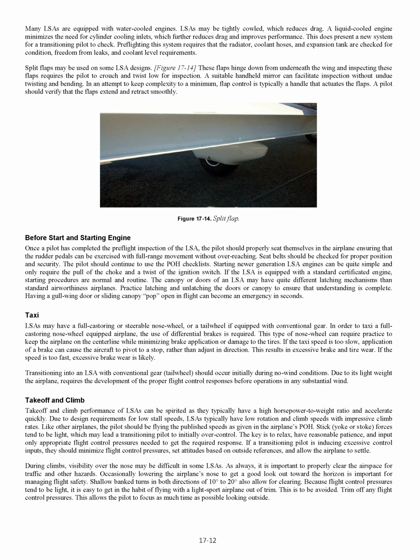These flaps hinge down from underneath the wing, and inspecting these flaps requires the pilot to crouch and twist low for inspection. A suitable handheld mirror can facilitate inspection without undue twisting and bending. In an attempt to keep complexity to a minimum, flap control is typically a handle that actuates the flaps. A pilot should verify that the flaps extend and retract smoothly.